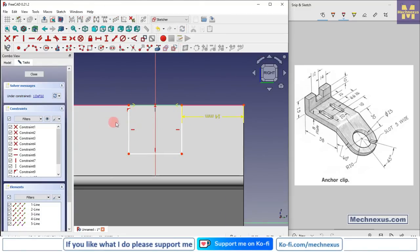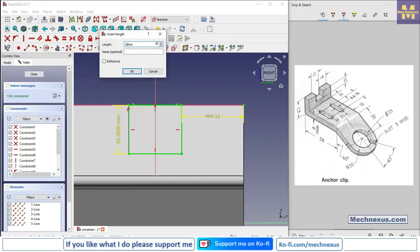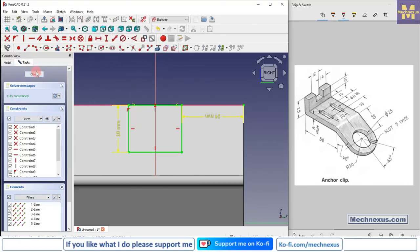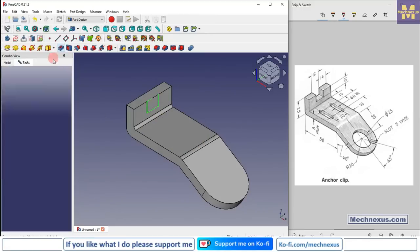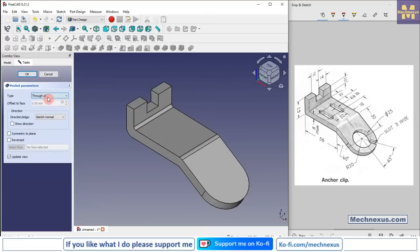and we will provide the vertical dimension of 10 mm. Click on close, and we will select the sketch, click on extrude cut, and from here we will say through all.